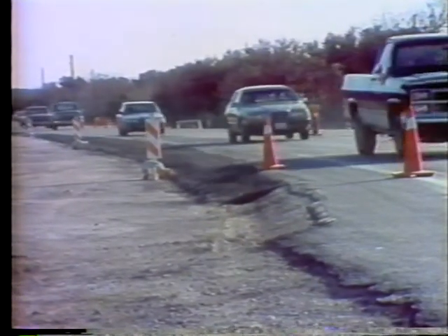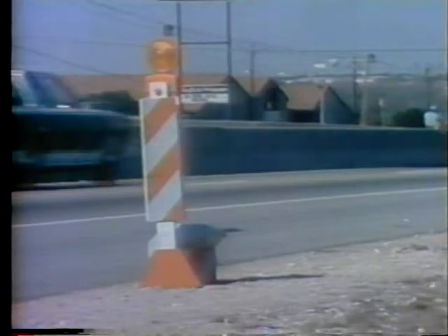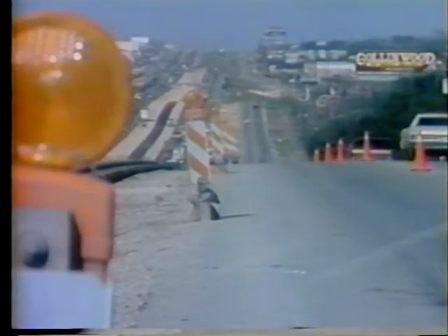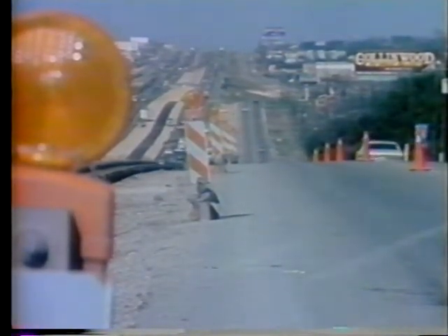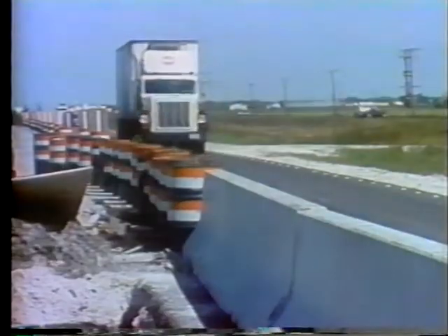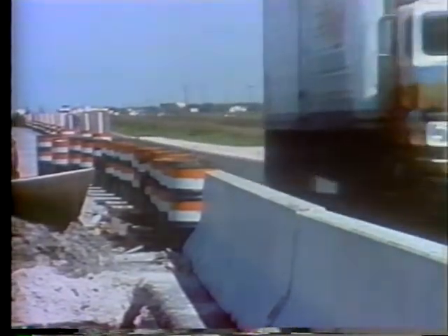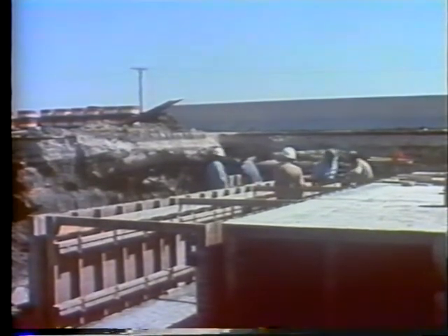An alternative method to reduce the danger of edge drop-offs is to place appropriate channeling devices and signs along the hazard. Maintain a 3-foot wide buffer between the travel lane and the drop-off. One of the best methods for handling edge drop-offs in long-term operation is the installation of a portable concrete barrier.